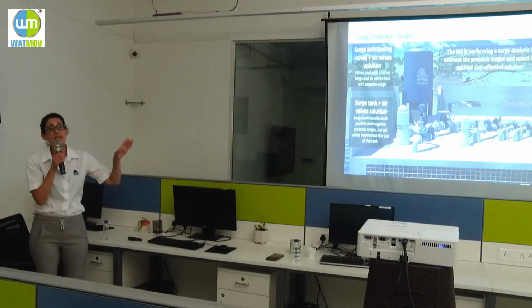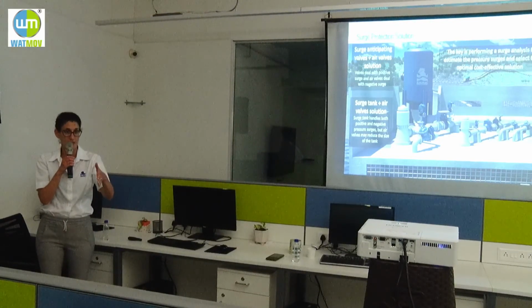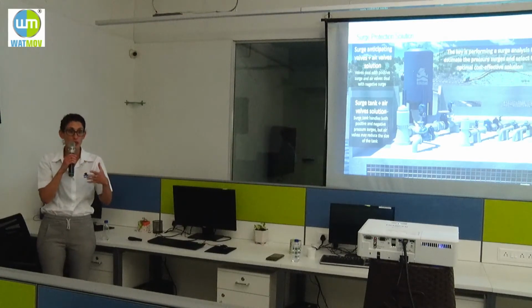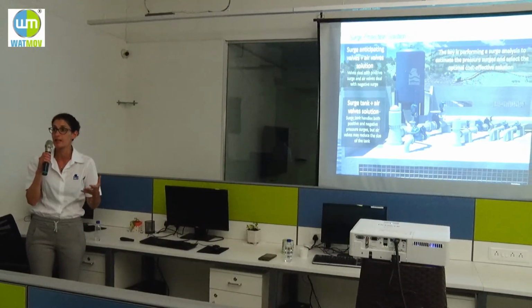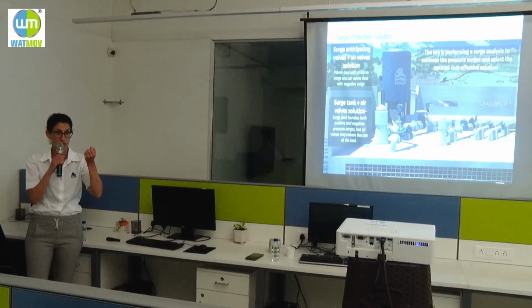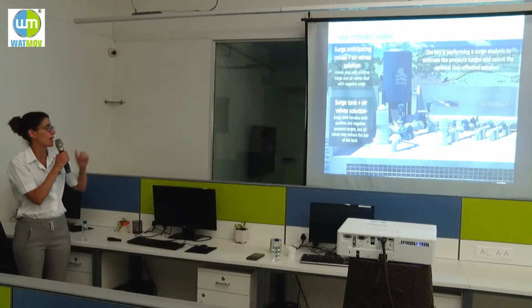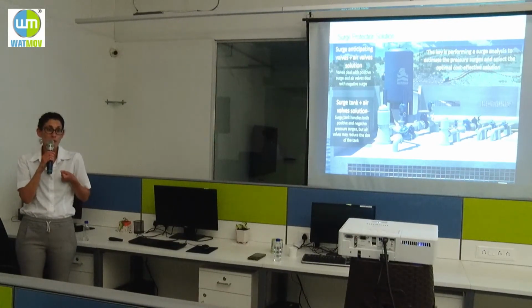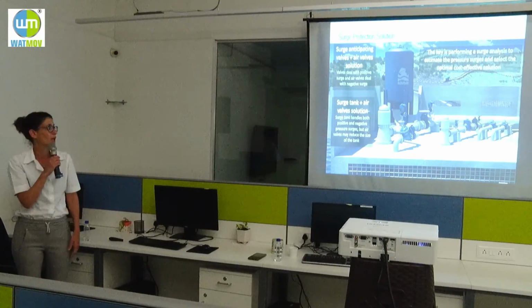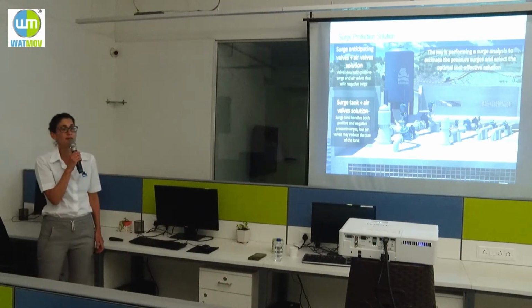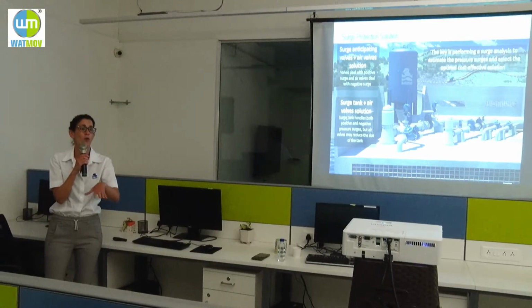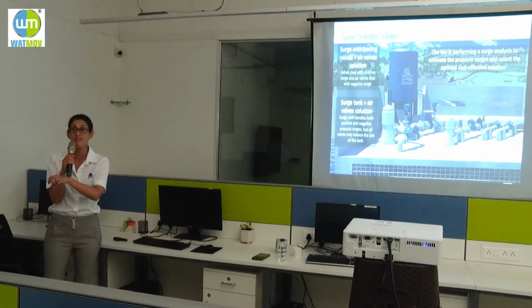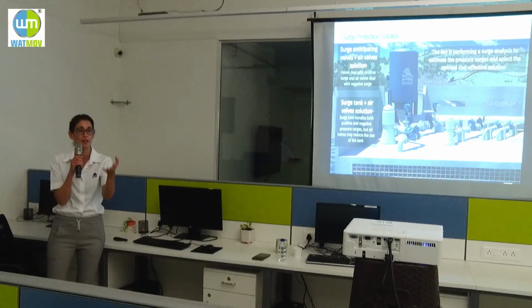And the surge vessel is actually treating both negative and positive waves. It's a vessel that is partly filled with air and partly filled with water. We're taking advantage of the fact that air is compressible. This is another solution that absorbs rather than dissipates. I can say that if we already have a surge tank, or we are designing and going for a surge tank solution, installing air valves will minimize the volume of the surge tank that we require.